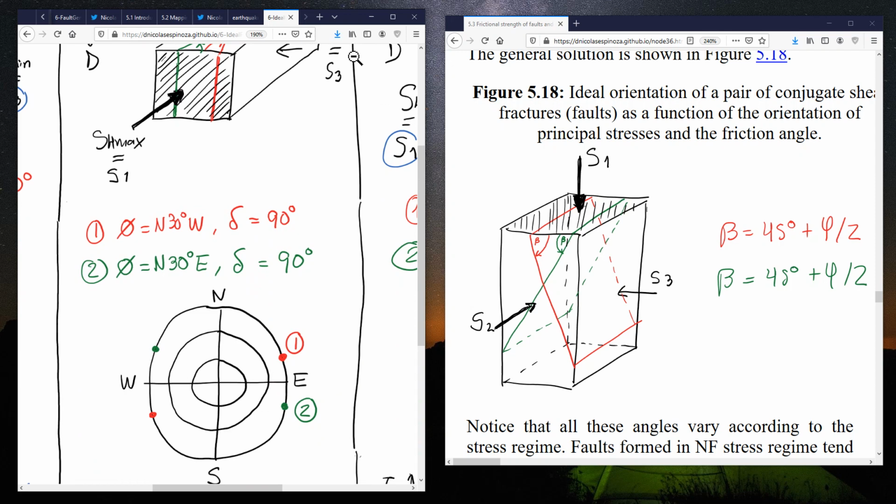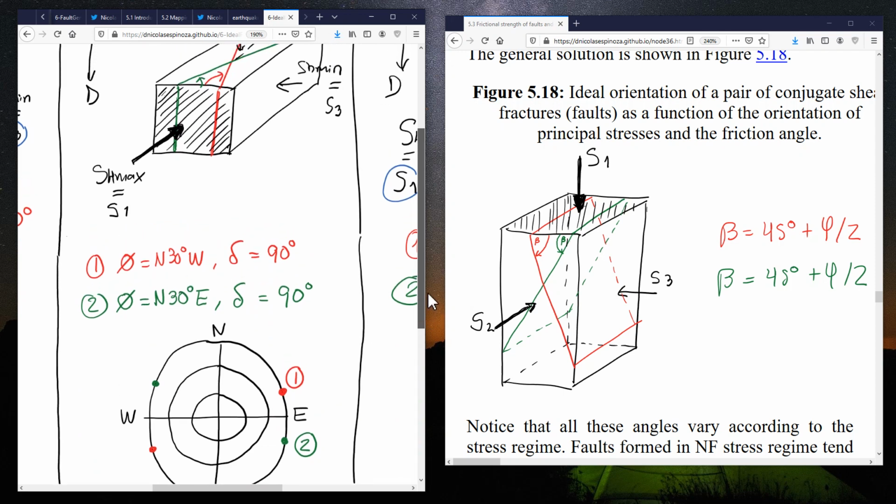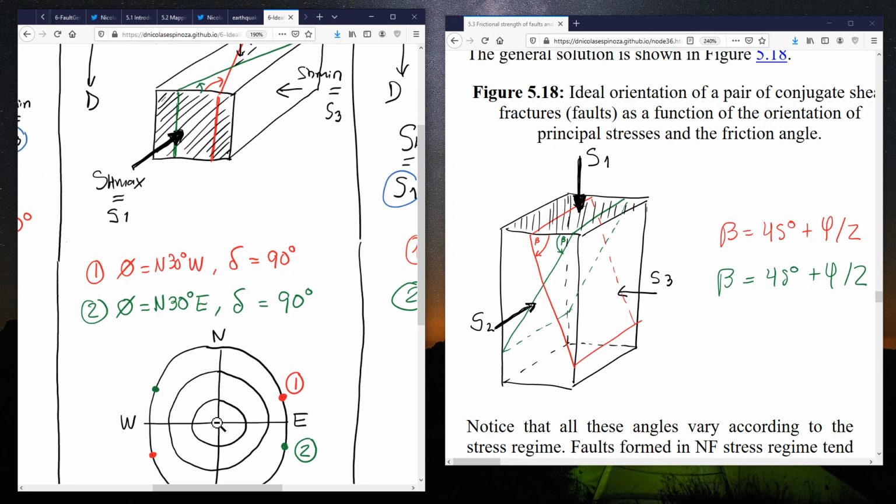And you may wonder now why we see two dots. Well, I'm assuming here that the dip is exactly 90 degrees. So if the dip is exactly 90 degrees, then this strike line, the red, is going to go from here to there, following my cursor right now. And since it is exactly 90 degrees, it could be either here or there, because both of these possible solutions are 90 degrees. If I have 89 degrees, then probably it's just going to be on one side and not the other. For the green one, the strike line will go through here.